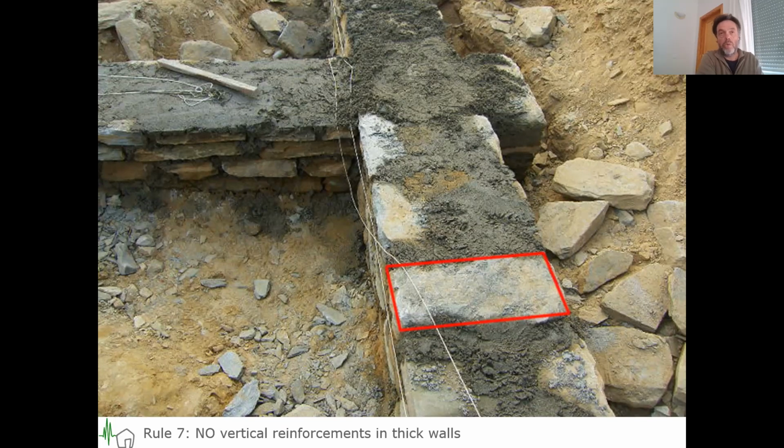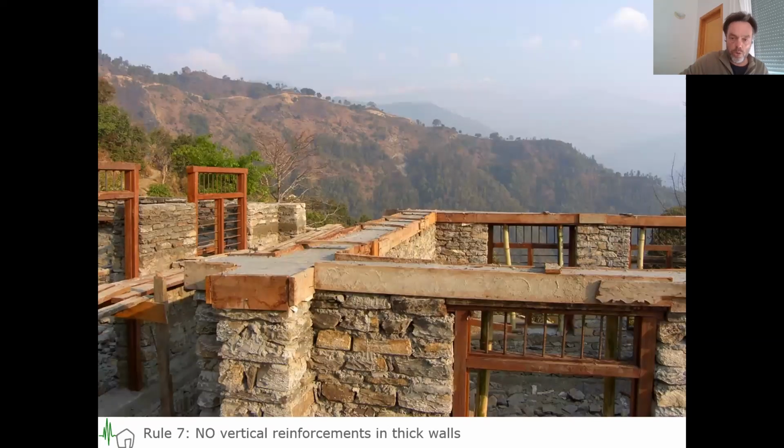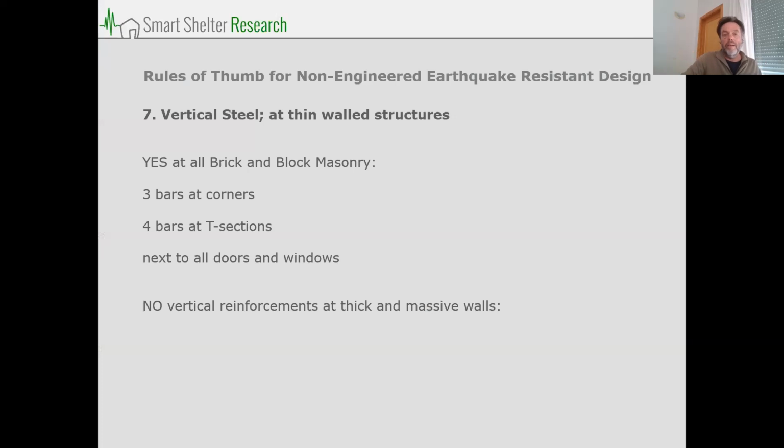Of course, that's more expensive than mud mortar. We know that. But this combination of elements for us was enough. So in our schools, there's no vertical steel sticking out. Like I said, I'm coming back to this in the second presentation. So we said, okay, we invest in good bonding, through stones, and cement mortar.